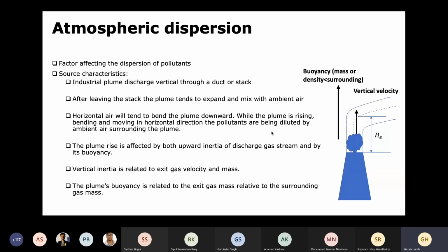So when we would like to know what is the emission rate from a stack and what would be the concentration of any pollutant in downwind direction, say XYZ distance from the stack, then either we have to do the monitoring at that XYZ places. That is one way. The other way is after knowing the emission rate, that means the gram of pollutant emitted, we can also use the dispersion models to estimate the concentration of any pollutant at any downwind distance.